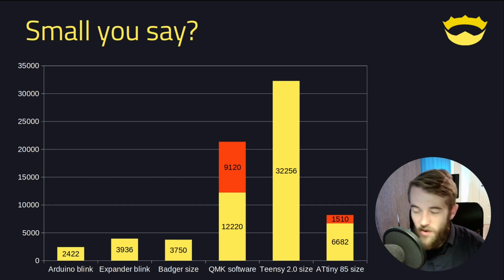And you might think, well, if I only want to use it as a keyboard, what does it matter? For one, you can add a lot of features. When your base size is this small and adding new features is comparatively small, you can have your keyboard do a lot of stuff. This is all over I2C, so I can connect I2C sensors of all kinds. I can connect a display, I can add a lot of devices, and they can all be controlled by the same microcontroller.